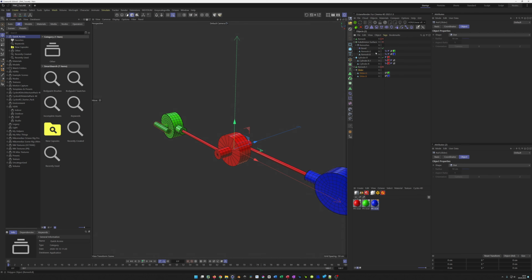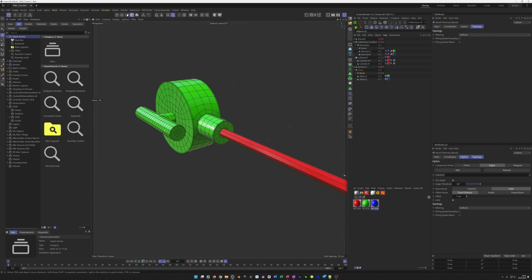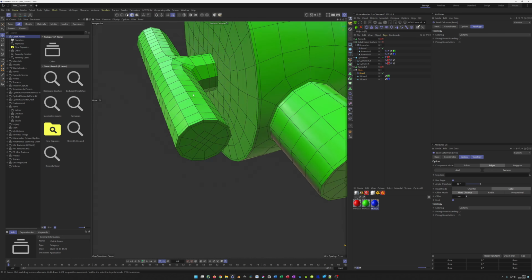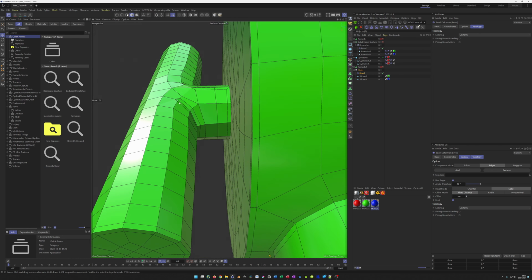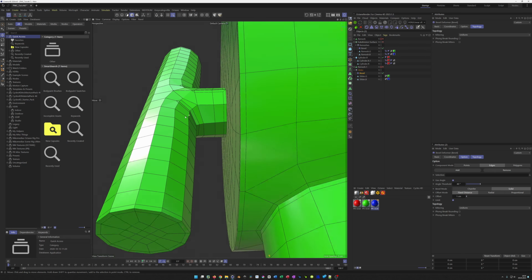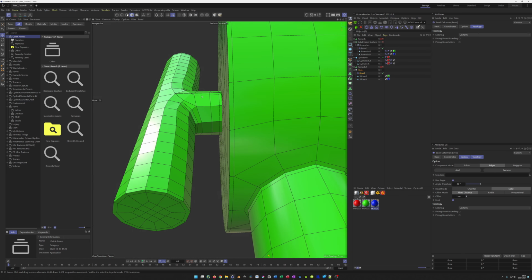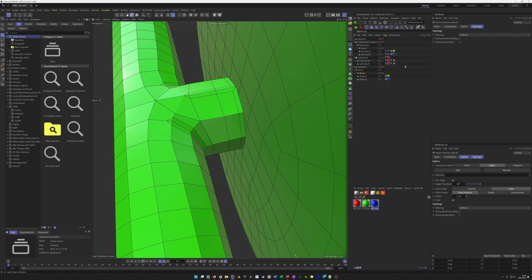So now we can put these two sliders in the null again, so I use one bevel. Slider, save, copy out this bevel here. And I should have a nice bevel around here. But you see, we have a problem now, we have edges here. I don't want it because this is enough for our bevel, I don't need the edges here. Here we have an edge where it shouldn't be, so I simply go to my bevel and use angle selected and make the threshold just a little bigger. Almost 90 degrees, so let's say 80.